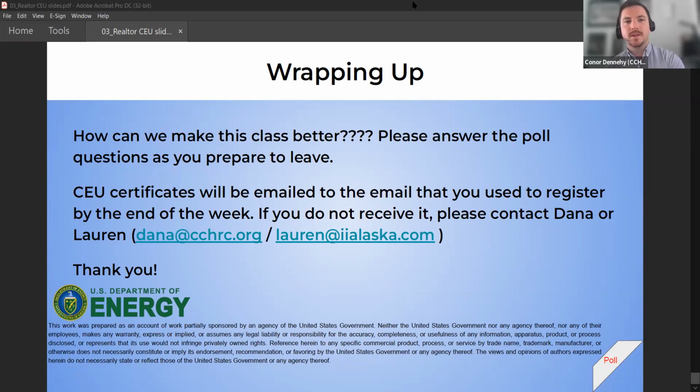We talked a little bit more about those in the builder class a couple of days ago, because we were thinking about when they're putting them in. If somebody puts a heat pump in a bad location where the snow slides off their house, then they might have some maintenance for clearing snow. But those are specific to them. As far as heat pumps in general go, if it's in an ideal location, the only maintenance the homeowner is doing is cleaning that filter.